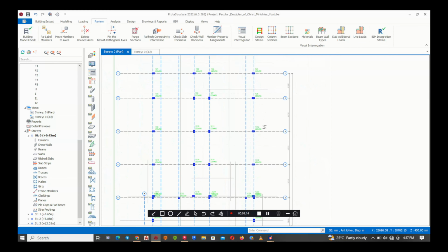Because when you have too many column bases in a project, there is a very large room for mistakes. For example, when you have a column here 1300 by 1300, another column here 1200 by 1200, another column here 1300 by 1300, another column here 1250 by 1250, and having different column loads and pad bases like that, it will give the construction engineer some kind of headache, and it won't even be economical, because when you are calculating for the artisan that is going to make the formwork, he will be calculating it one by one. It won't be easy to group together. Okay, so that's the whole essence of this video.